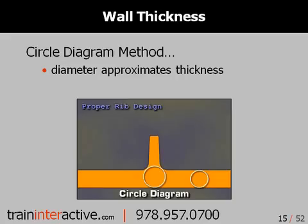When using this circle diameter in a theoretical cooling calculation, the cooling time increases 70% over that of the main wall. So to sum up, we try to reduce variations in circle diameters in order to minimize sink, provide structural integrity, and to approximate the cooling time. To conclude this part of the discussion, cooling time is dependent on the thickest part of the part, increasing the importance of maintaining a consistent part thickness.